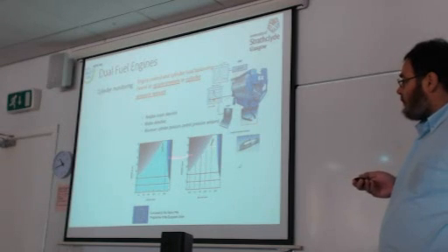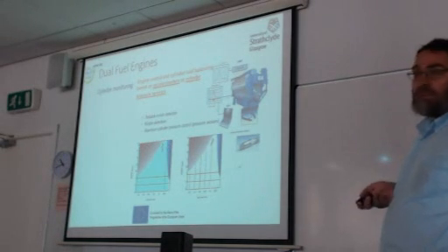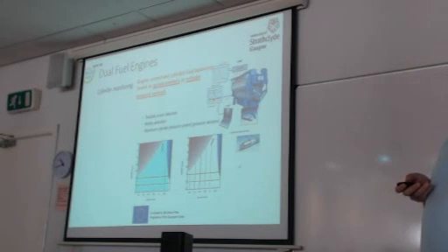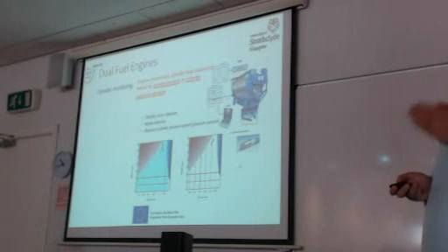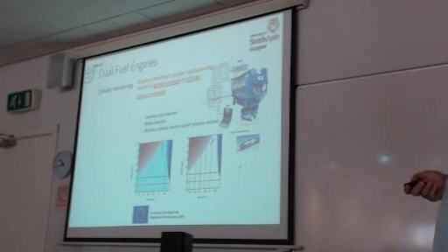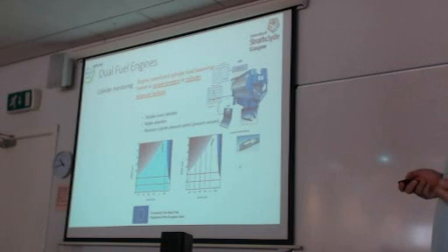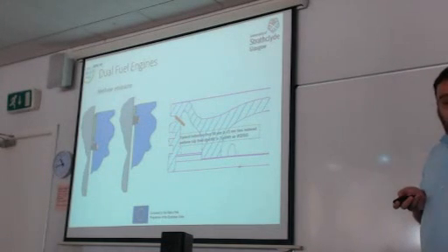So in this case, the pressure inside the cylinder and acceleration in various parts of the engine are recorded, ensuring that the engine operation, I think this is the case of constant speed, this is the case of variable speed, is according to the specification within this lambda window. So this is very important. This is another obligation, an additional requirement for installing sensors monitoring the engine, which does not exist for the case of diesel engine.